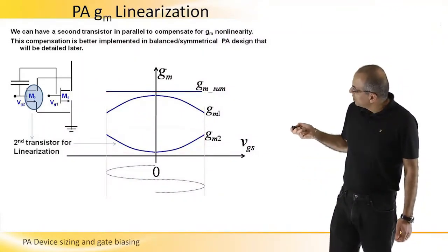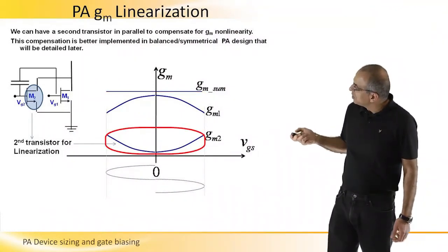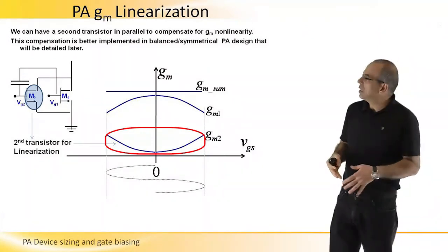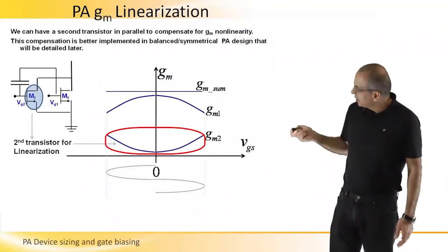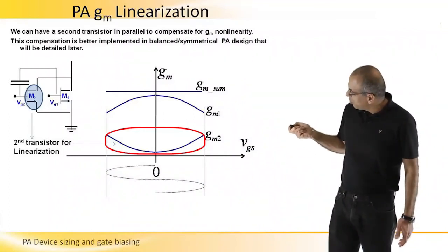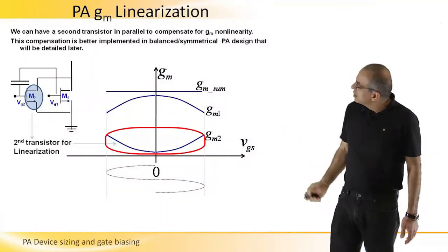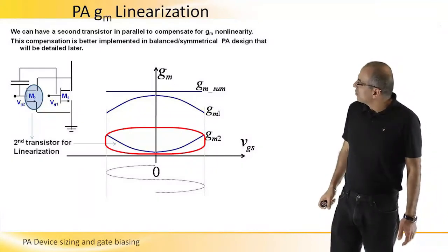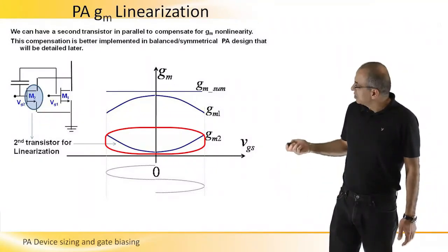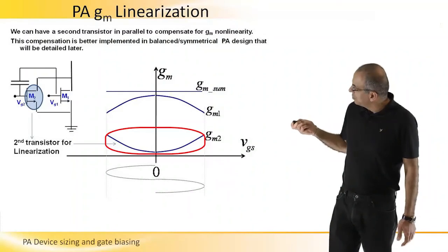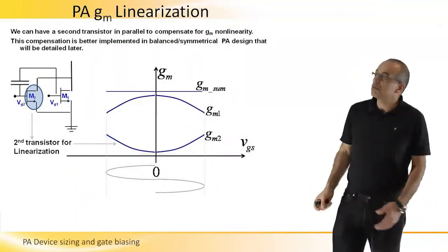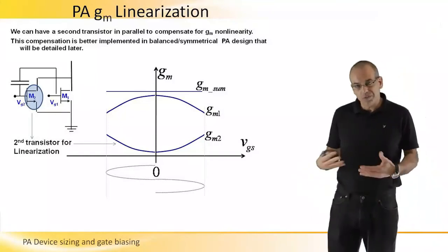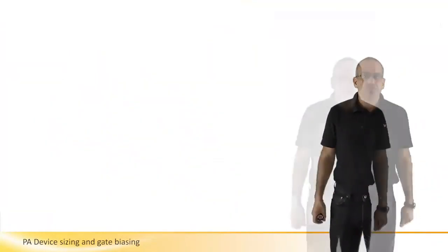However, this behavior is easily achieved in balanced or symmetrical designs rather than single-ended designs. It's not very easy to find this performance in a single-ended design transistor, but it is achievable, and it's being employed. This linearization technique is being employed in differential or symmetrical PAs.